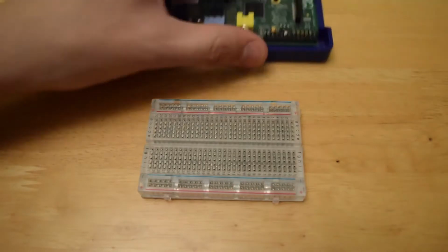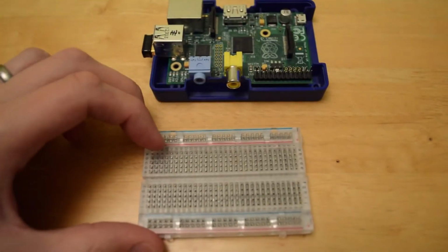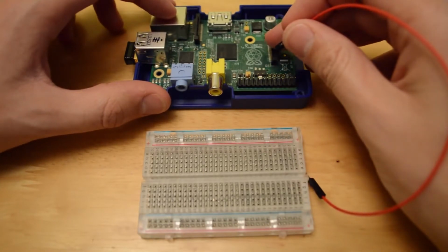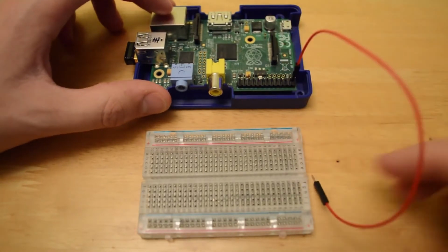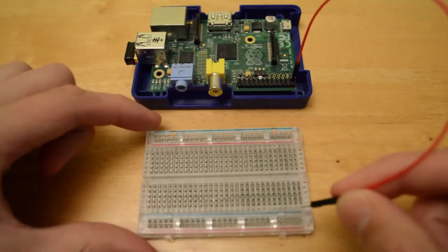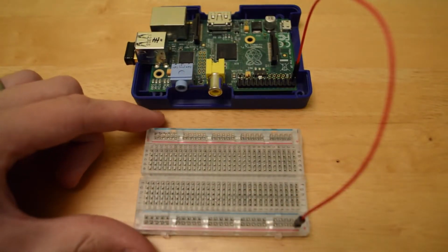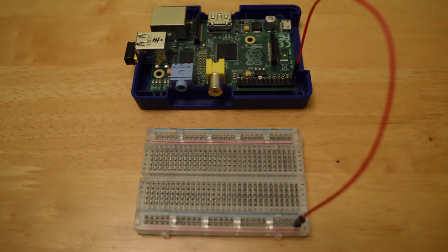So let's grab our Raspberry Pi and start connecting our GPIO connectors on the Pi to our breadboard for the first time. So we're going to put this in pin 1, and then we're going to connect up pin 1 to the red voltage line, which will activate that entire line horizontally across the breadboard, giving it a 3.3 voltage.